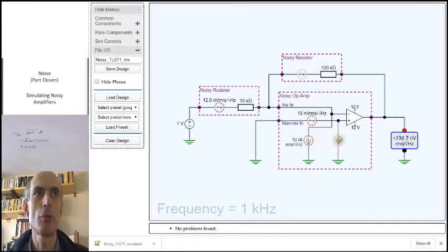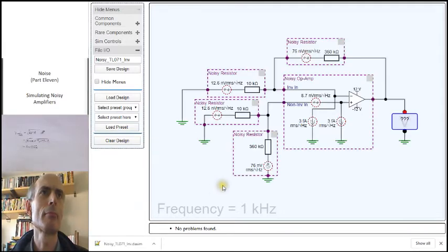These two currents really are insignificant, and this noise feedback resistor here doesn't add very much. Really not a significant difference to the output noise adding that resistor in. You can make more complex models as well. This is a model of a differential input amplifier based on the MCP6291 op-amp with a gain of 36.